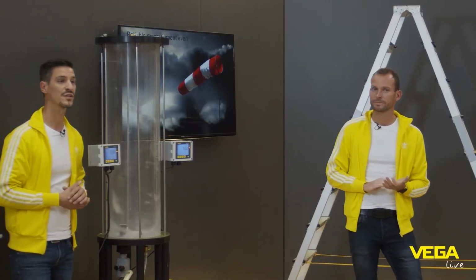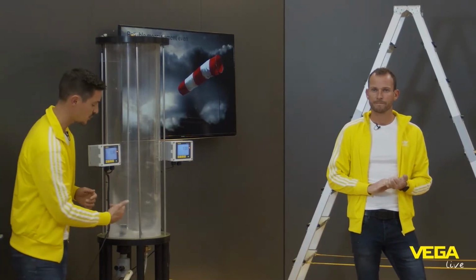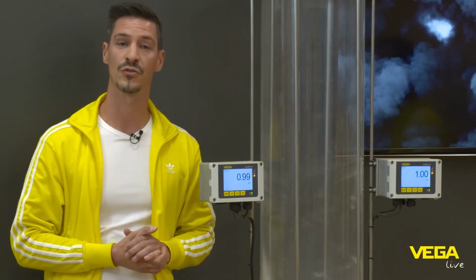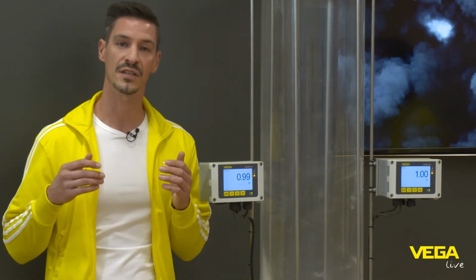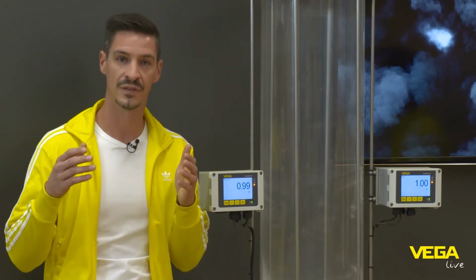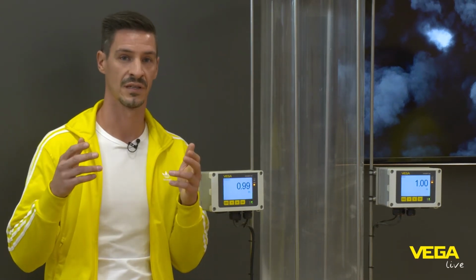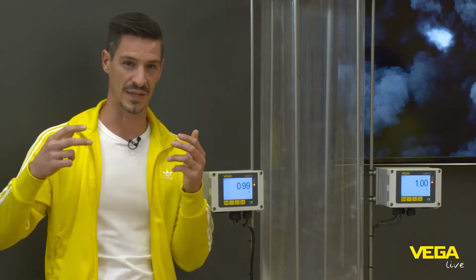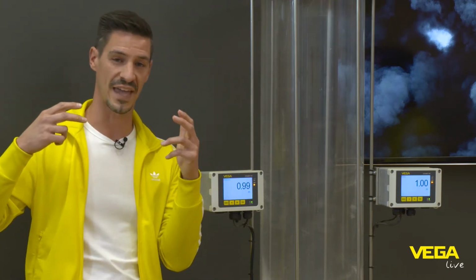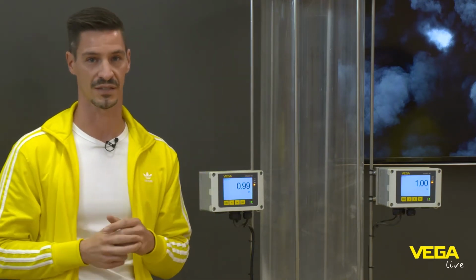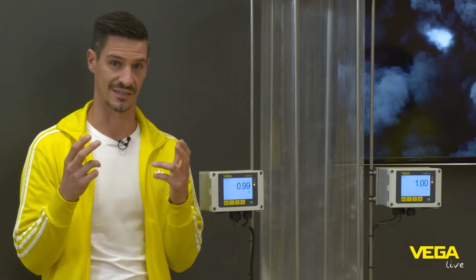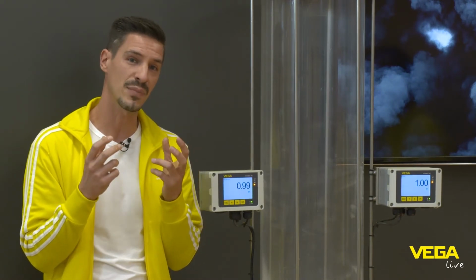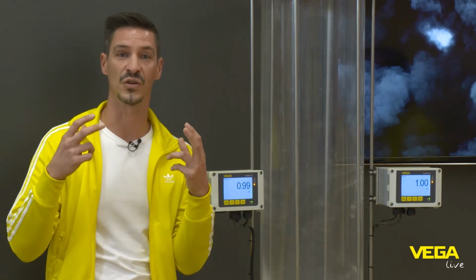One further influencing factor we have already seen within this tube is the dust itself. Clemens already mentioned it. Ultrasonic creates an ultrasonic wave, and this travels through the air. Now we have some dust particles within this air, and this mechanical wave has to move the air and the dust particles. This takes energy away. So the dust damps the ultrasonic wave.